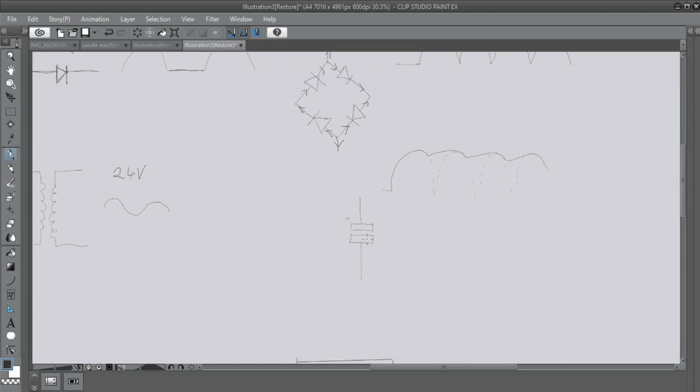So for this, we're going to use an electrolytic capacitor. An electrolytic capacitor will store electric charge, and it will act as a tank that will take some time to fill up, but also some time to dissipate this charge. So after going through the electrolytic capacitor, this is how the wave will look. It will stabilize more around a higher voltage point, and it won't fluctuate as much.